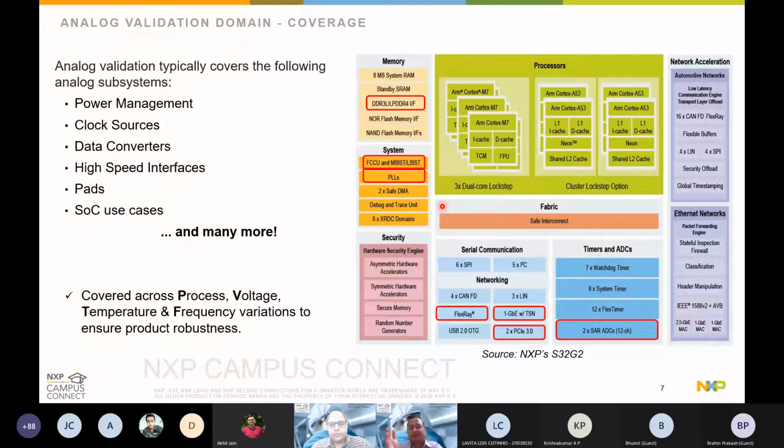So the analog has to be converted to digital, and the post processing is done. So all the key interfaces are analog. For example, if there is a memory, which is let's say DDR, it will have a physical interface. When I say physical interface, the physical layer is basically what implements the electrical functionality of the interface, voltage swings and timings and so on. So this is where the PHY interface comes in.